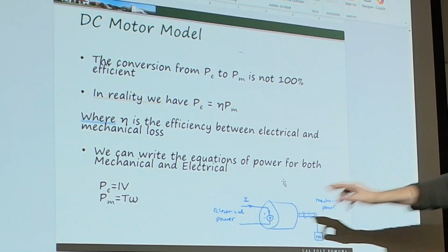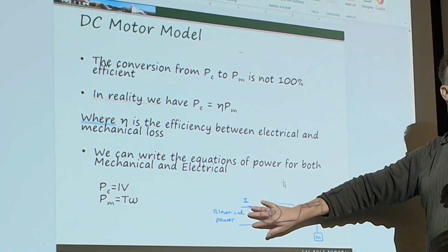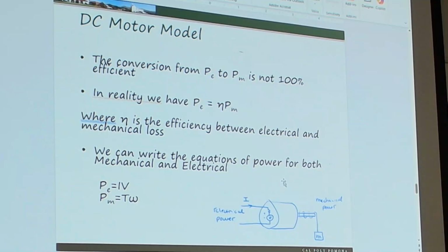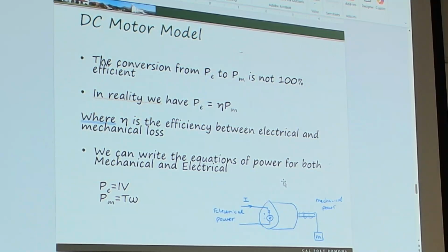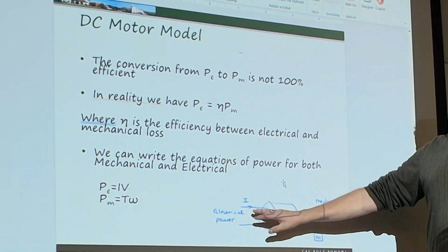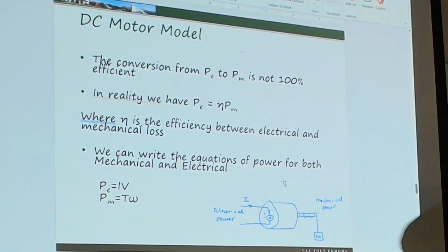So this guy right here is a governor or a throttling of the load, because that back EMF is now going to get higher as I apply more voltage. We haven't talked about voltage yet. I'm just going to give you a little bit of a hint right now. The faster this spins, the more back EMF I've created, right? That's going to keep my motor from ever exceeding some maximum rotational velocity. It's a feedback system.